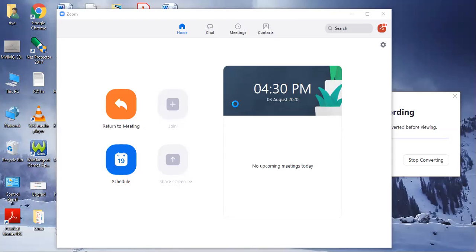So basically what we're trying to do is create the surfaces for adhesion. I have showcased two ways. One is from the surface menu itself, with two options: an elliptical patch and a freeform patch. For freeform patch, it's like a freehand curve that you draw around the surface that you want to create. Elliptical patch is more defined. Basically, by left clicking and dragging the ellipse, as the name suggests, anything within the ellipse shall be encompassed in the surface.